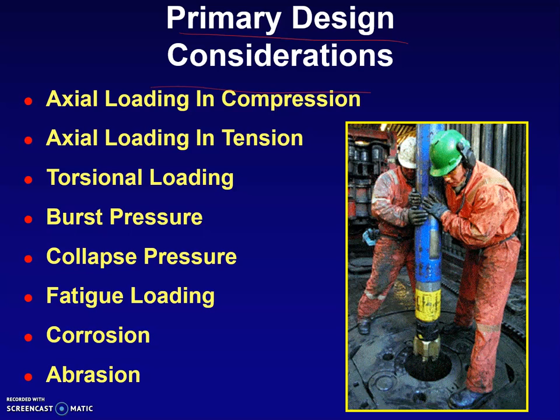In order to design it, your drill pipe will be under significant axial loading. For example, consider that you have a piece of pipe all the way down hole, and let's say this is 10,000 feet, and the weight of this drill pipe is, let's say, 24 pounds per foot. So this drill pipe will have a weight of 24,000 pounds force. That's a huge weight. So there is significant tension in the pipe, especially near the surface.